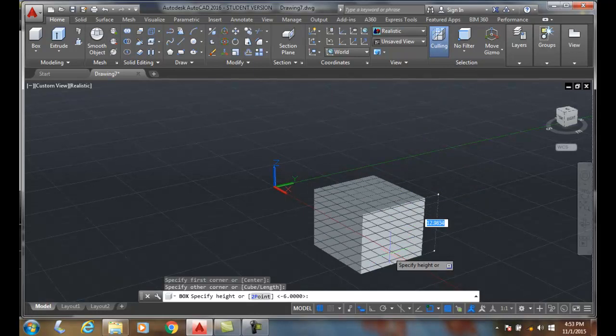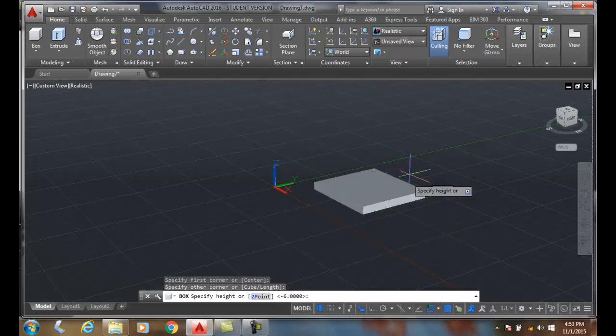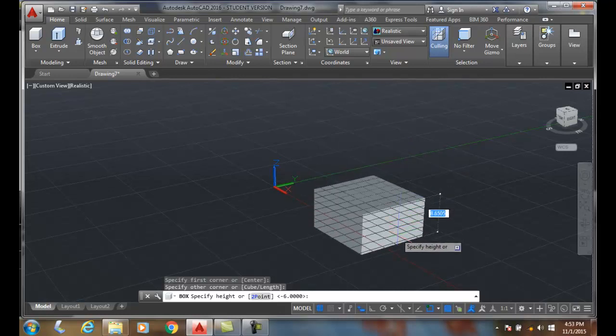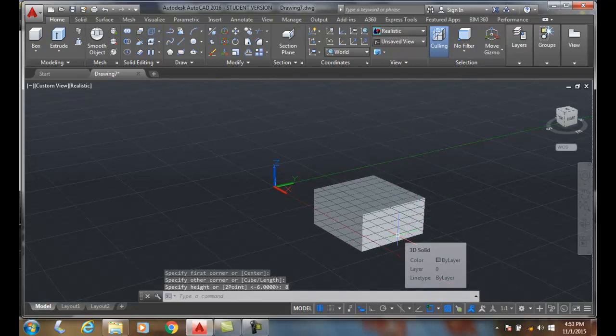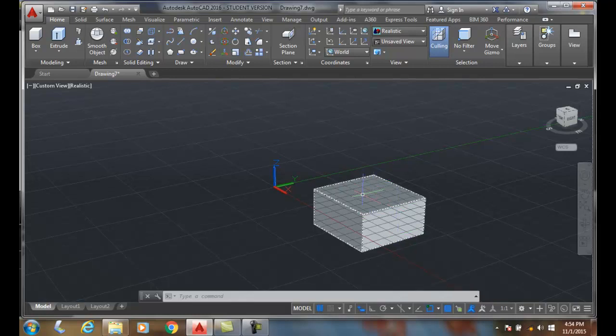Now, once I have put the values in, such as 8 for example, I hit enter, then that enter sends that to AutoCAD for it to apply that to the drawing. So we use dynamic input, which allows us some dynamic feedback so we can visually see what it looks like on the screen in 3D.